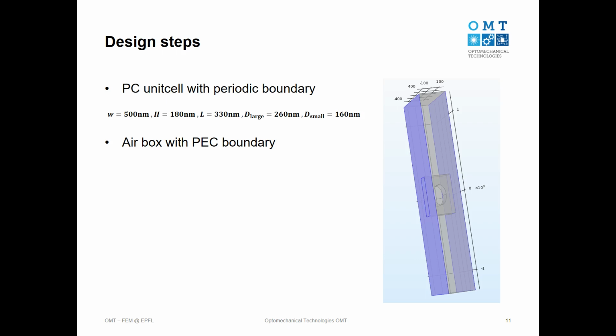And for your model, remember that you should always consider the surrounding area because the light can propagate in the free space. It's always good to limit your structure in a way that it matters. For example, I don't want to put these PECs very close to the structure because they would disturb the field, so I want to put them as far field as I could.